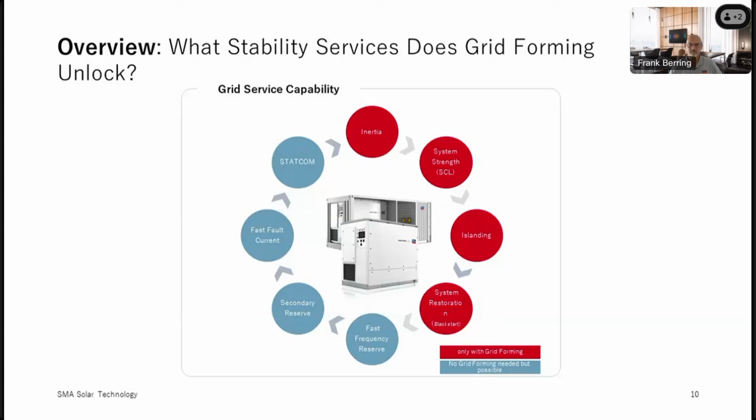Sounds good. The next one: which droop mode is more common in grid forming applications, U of Q or F of P? Well, the F of P, of course, is most commonly used, but we use both. Both have to be used because voltage and frequency are always fluctuating. So you have to use both in microgrid modes.